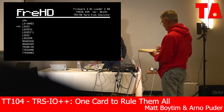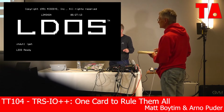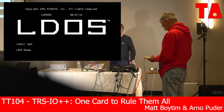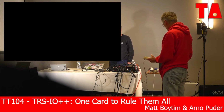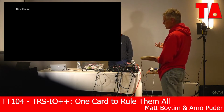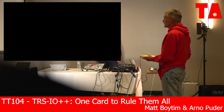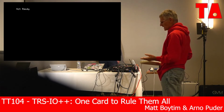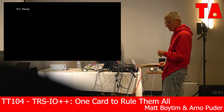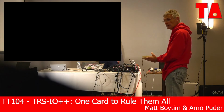Graphics. Let's try one of those. So the sound is both on HDMI and also on the 3.5 audio jack. On the audio jack, we mix the Orchestra 8590 sound in stereo, and on the cassette jack, we mix it down to mono. And again, that's another interesting aspect, because this turns out to be 8-bit linear PCM audio. How do you output that from a single bit cassette port?